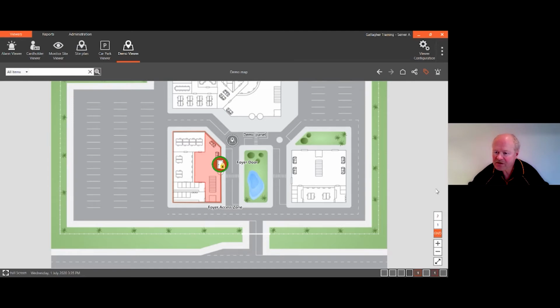When creating an irregular shape, if you hold down the control button, the lines will lock at 90-degree angles. So that's another good one, if you're trying to work your way around those shapes and having a bit of trouble getting the corners and things, then that may be a quicker way. Certainly with a bit of practice, you'll get pretty fast at working your way around irregular objects.